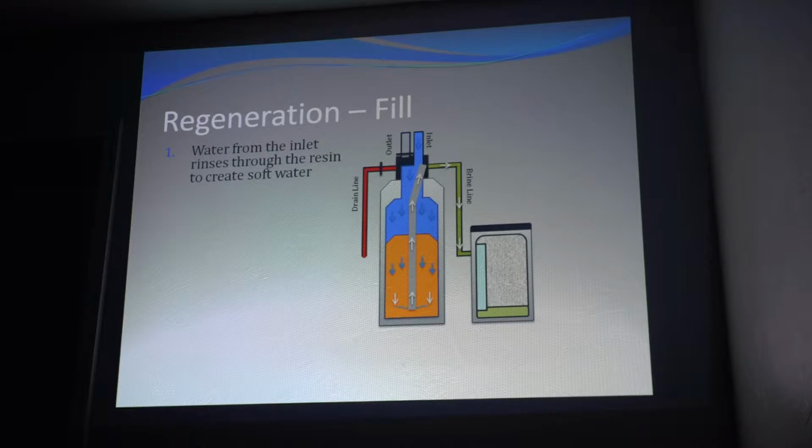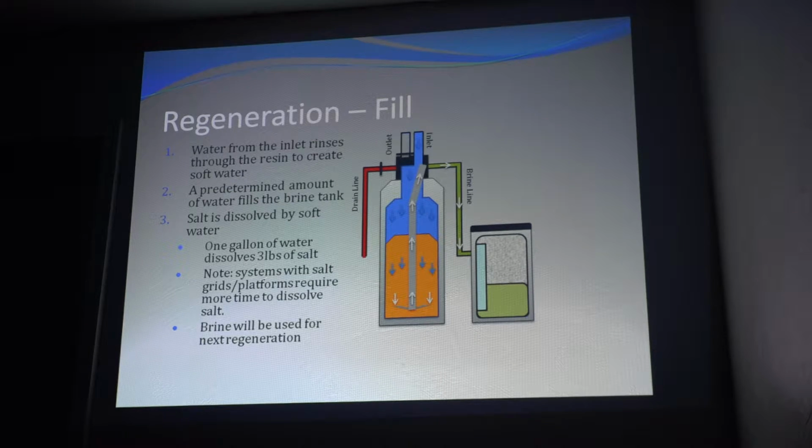And then fill, or some people call it refill, same thing. Water from the inlet rinses through the resin to create soft water. Once again, on a twin tank system, the brine tank refills with soft water as well. So you keep your injectors cleaner, you keep your brine tank cleaner. A predetermined amount of water fills the brine tank.